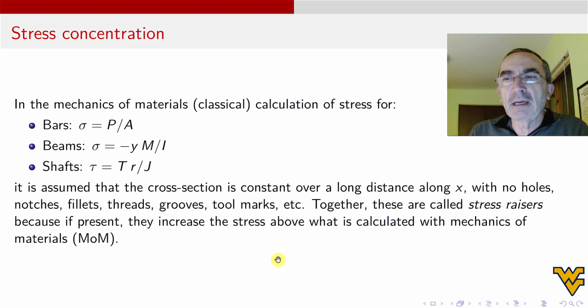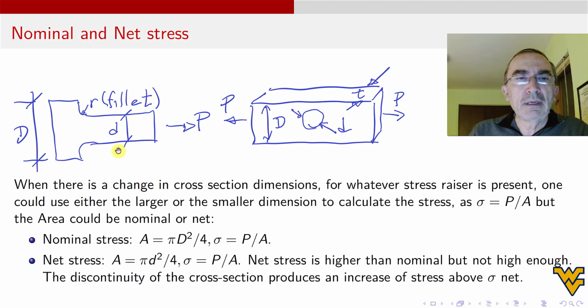All right, since calculation with mechanics of materials is very easy and we can do that fast and accurately and confidently, we would like to see if we can calculate the stress caused by these notches also in a simple and efficient practical way. Okay, so here we have two things. We have a shaft with large diameter capital D and small diameter lowercase d, and the change in diameter is accommodated by a transition with a fillet that provides a smooth transition between one and the other, and there is a radius for this fillet, and that is important in the magnification of the stress.